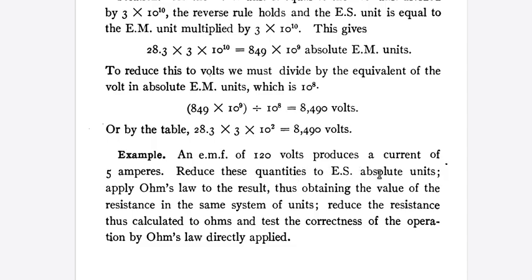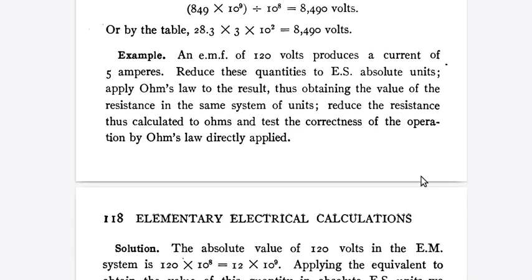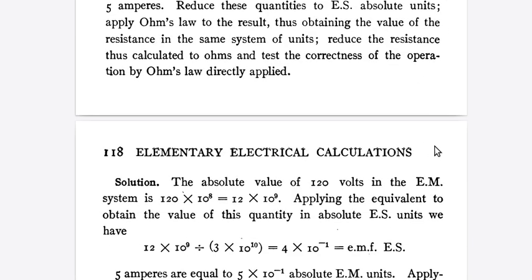Reduce these quantities to electrostatic absolute units. Apply Ohm's law to the result, obtaining the value of the resistance in the same system of units. Then, reduce the resistance thus calculated to ohms and test the correctness of the operation by Ohm's law applied directly.